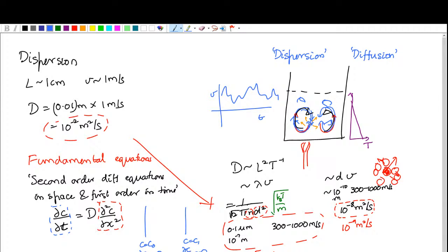Okay. So those are the fundamental equations that you require to solve. For example, for the mass, heat, and momentum transfer in a CSTR. So in a CSTR, you would have an inlet condition. Okay, at the boundaries, for example, on the walls of the CSTR, right? For the mass, you'd expect that there's no penetration through the walls, and therefore zero flux conditions will be applied for mass, except at the outlet, where whatever fluid is there in the CSTR is removed at the outlet.